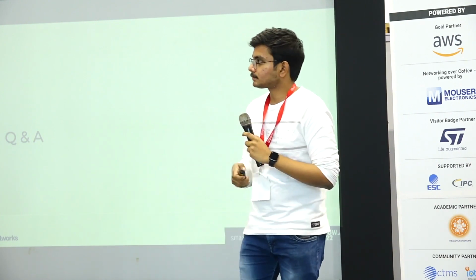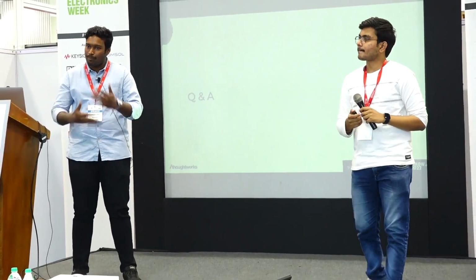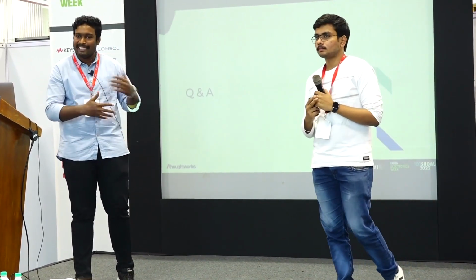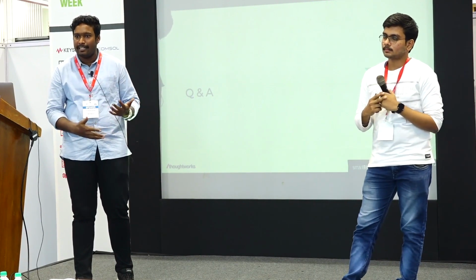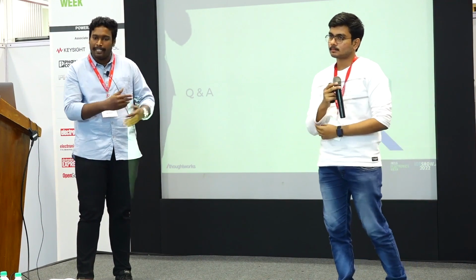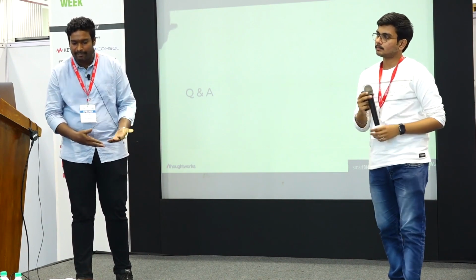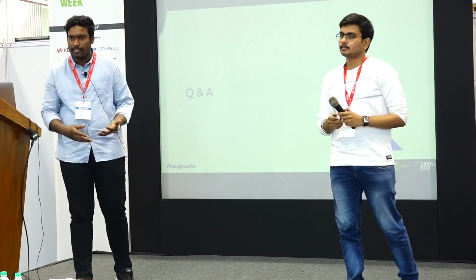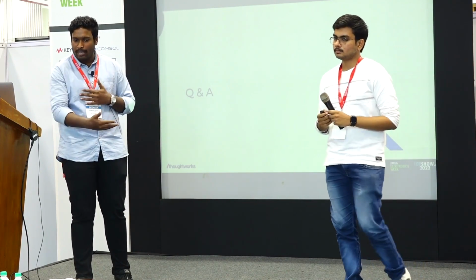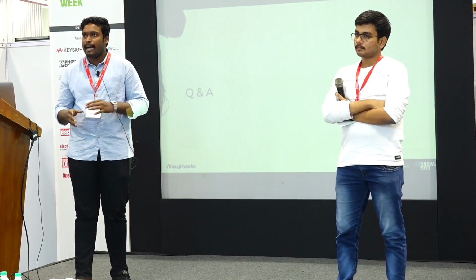And yeah, a reinforcement learning model is how you solve the problem, right? Before that, you actually need to model your bot. Modeling the bot is the other part, like the controller part. So how your bot is receiving the hardware, or creating the hardware abstraction layer. The hardware abstraction layer can be grouped into or embedded into the device itself, right? So you write the device drivers, you write controllers and other things, deploy it in the bot, and you just send the actual application commands to the bot, right?